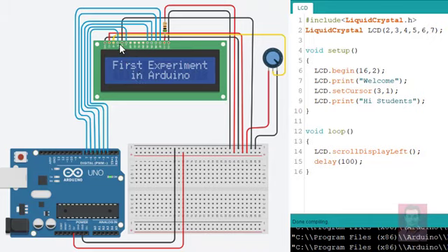Okay, moving further, this is a software version. In the case of the green one, the characters displayed are black. Since we have done the practical, we know that on an LCD the characters are printed in black color. Here they are printed in white color. Moving further, you get that RS pin. That RS pin is connected to pin number 2.